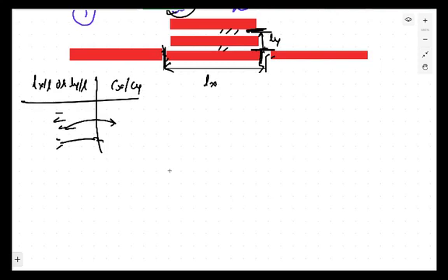But this particular lecture is common for both the examinations, because it is a conceptual lecture. You should understand all these things. So that's why I'm giving you the lecture. This is common for these two examinations. Fine. From here, you can calculate the Cx and Cy values, and after calculating the values, you can use them in the relations written above to calculate the value of stresses at the interior, edge and corner. Fine. These will be the temperature stresses.